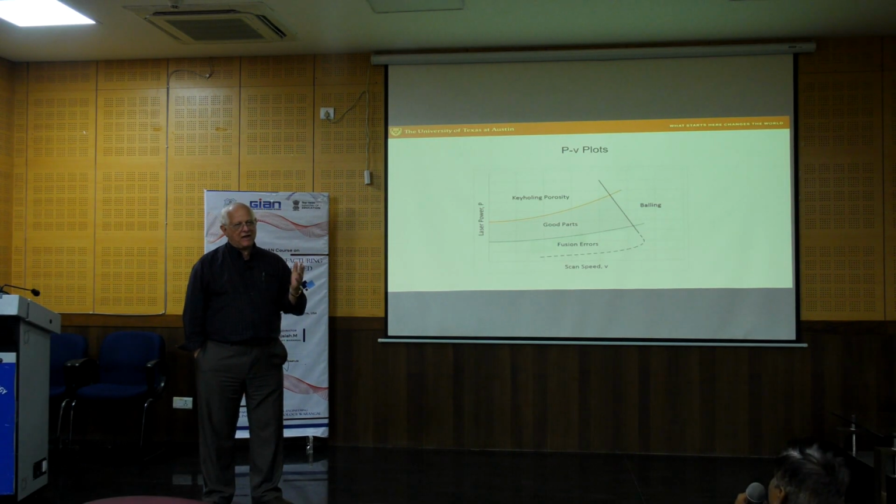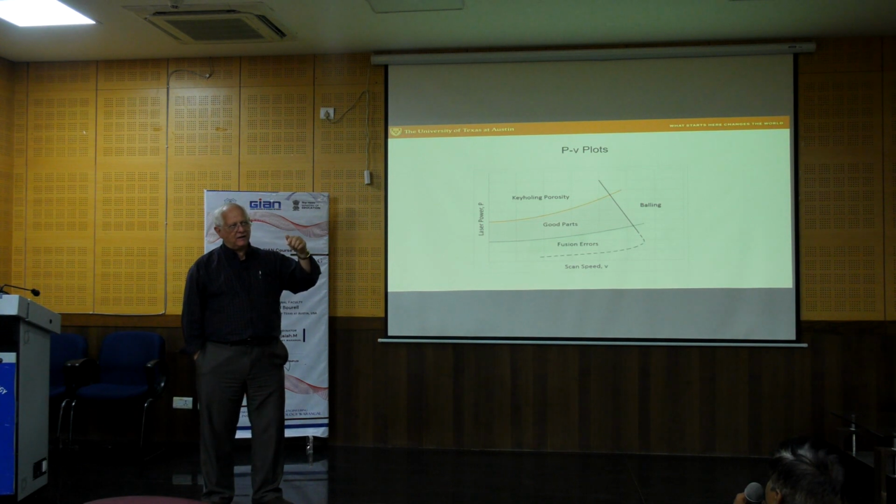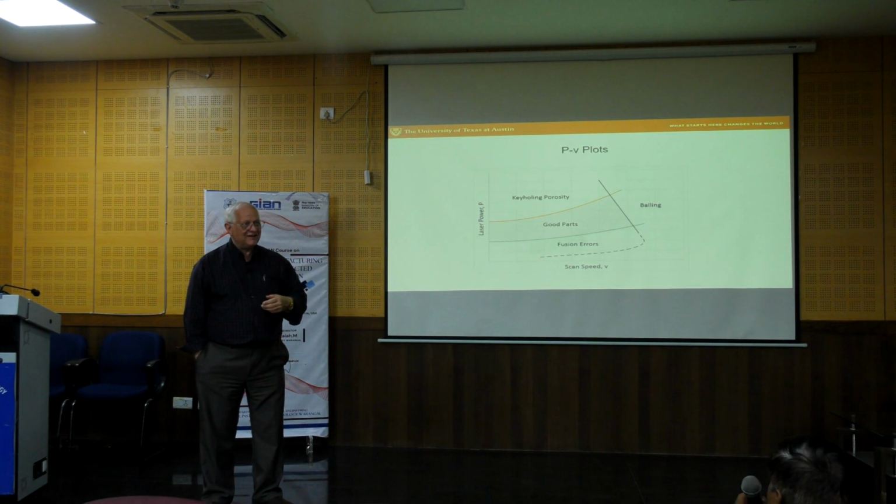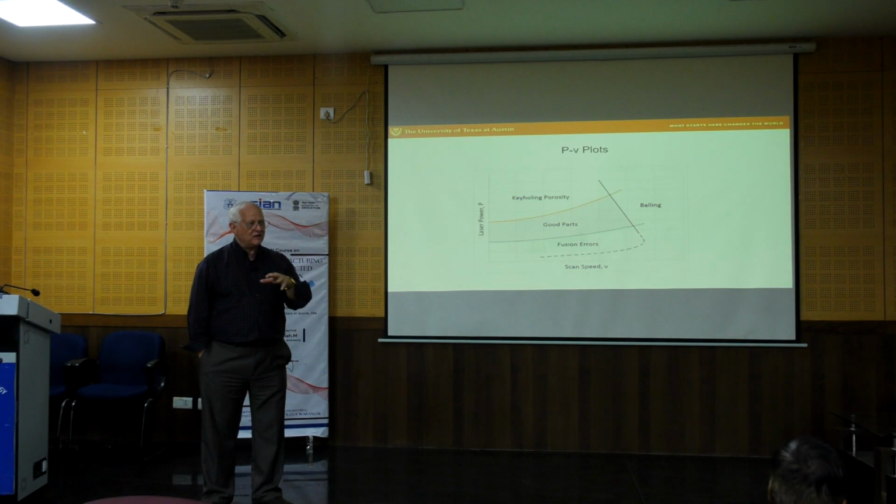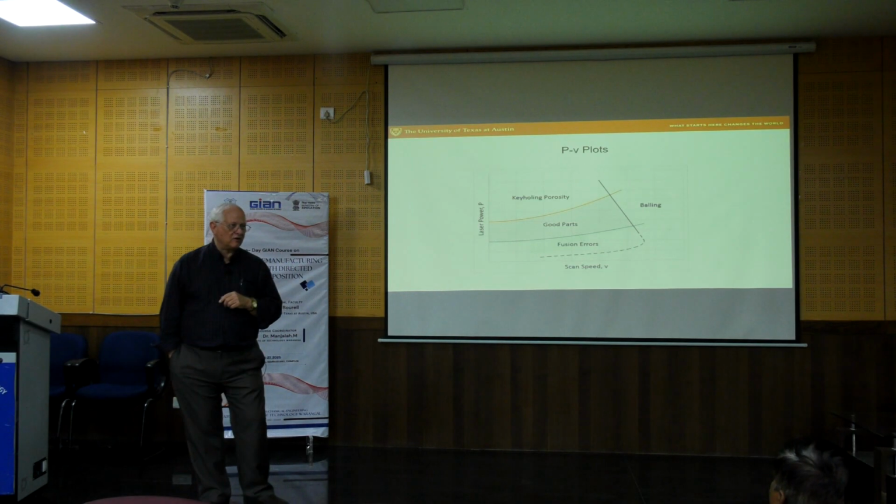I guess you can imagine the big distinction is the coupling, but like I mentioned earlier, we're sort of forgiven, at least with powder beds, which is typically the way additive works with metals. We get the mechanical coupling effect, which improves with the laser. You don't worry about that with the electron beam, but the laser sort of self-corrects because of the mechanical coupling.